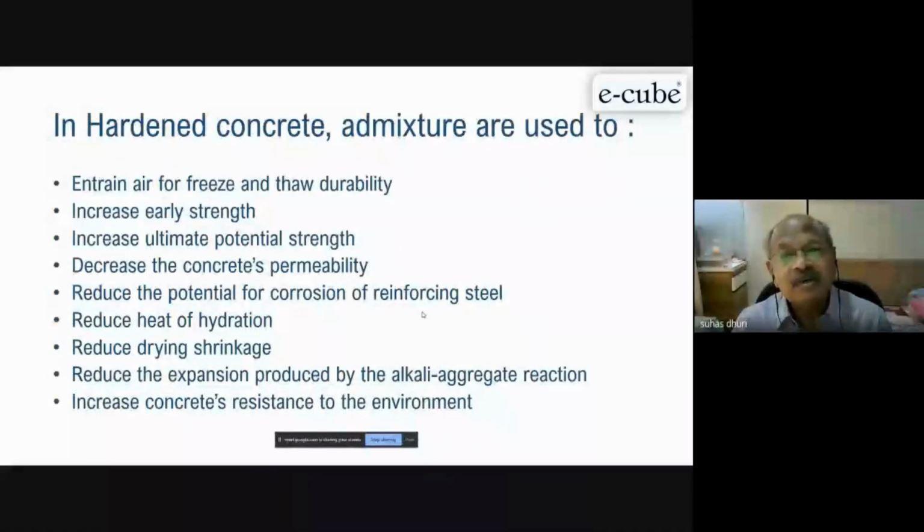When you talk about maturity of the concrete, we always say the datum temperature is minus 10 degree. So below that degree, concrete will not start hydrating. So once we get freeze, and then during daytime it heats, the whole cycle is called freeze and thaw. So whatever water is there in the concrete, once the concrete goes in the freezing stage, this becomes ice. Now ice has got more volume than water. Now if that is giving more volume, it gives some stresses to the concrete.